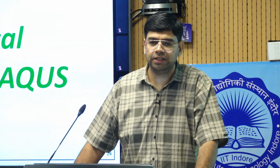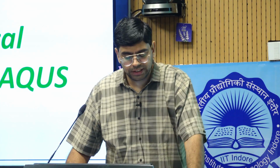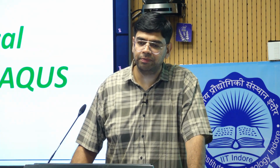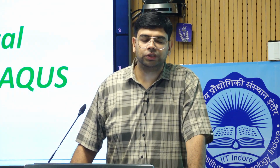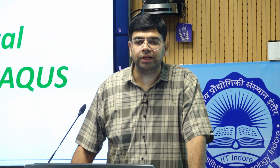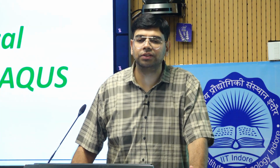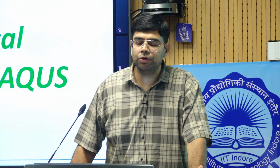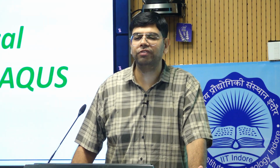Second step is clear. Third, I am giving a crude outline of the steps we implement in finite element. After defining the material properties, you have to assemble the components. These steps are common whether you follow ANSYS, COMSOL, or Abaqus. You assemble the components to form the final assembly.